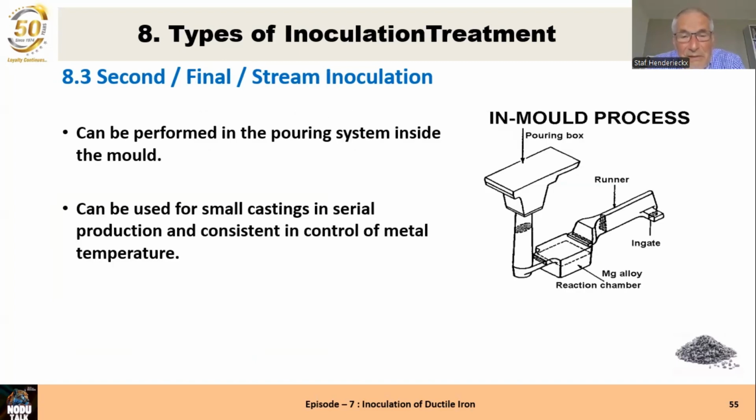And the last one is, of course, the in-mold process, where you can have, as with a magnesium treatment, the same system used, not for the magnesium treatment, but for an inoculant treatment. It's done for small castings and serial production. It's fairly consistent because it's always the same temperature and it's independent from your operator.